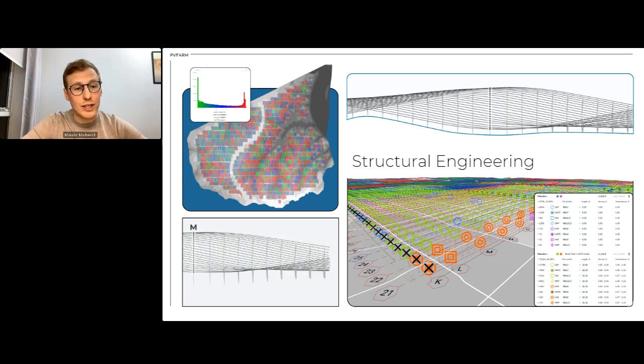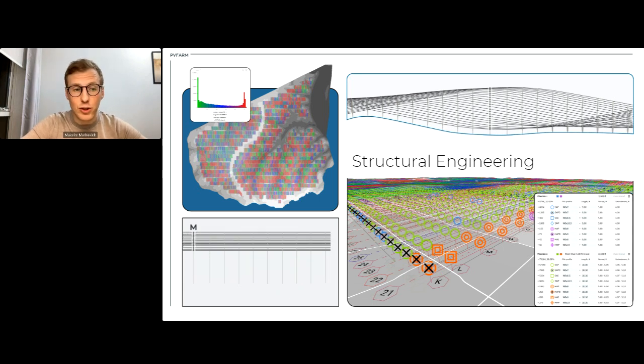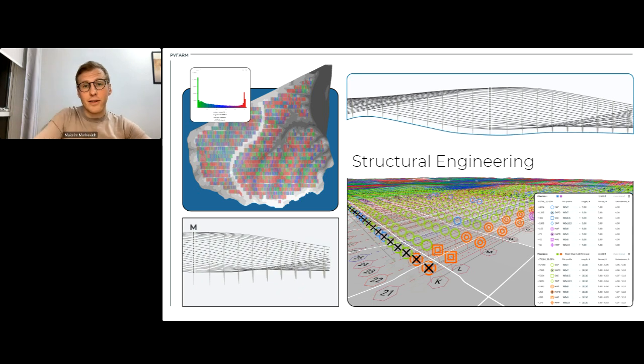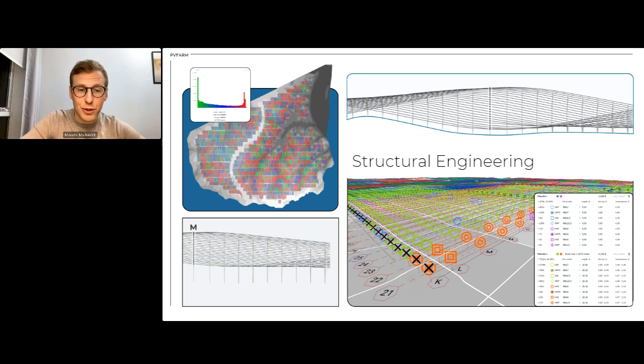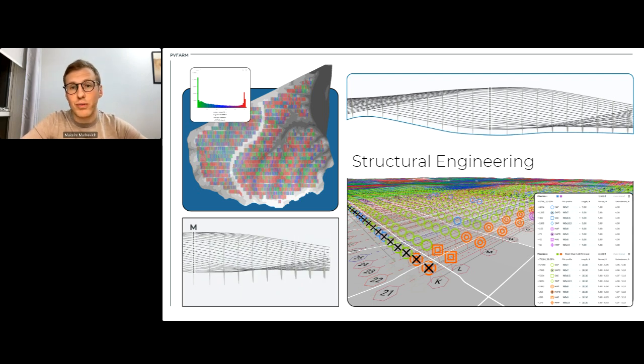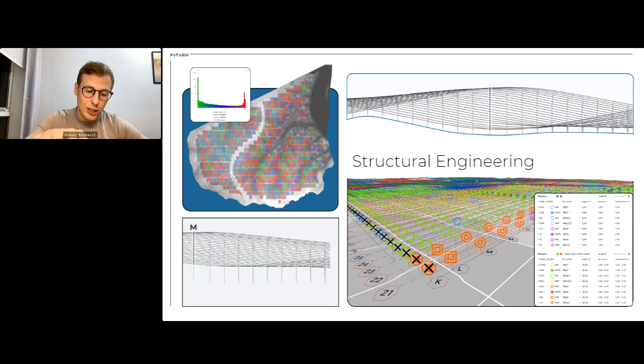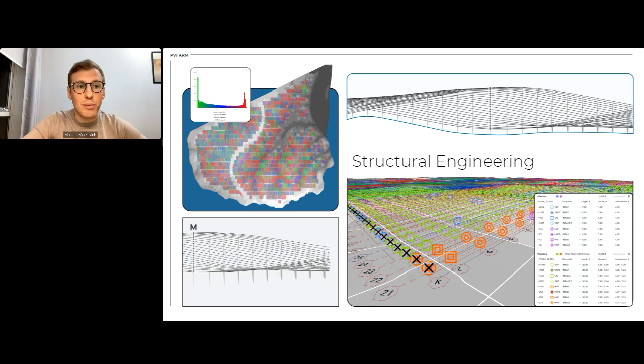They affect even tracker drive lines, for example. There are certain trackers with a drive line that needs to be aligned around the motor pile. You cannot see it in 2D, but you always see it in 3D, and the real world is 3D. That's why it's important to consider those things. So piles play a crucial role in defining the most expensive areas of the project, and in such a way, they influence the array placement and overall design strategy.